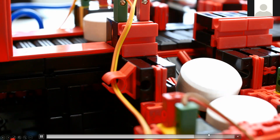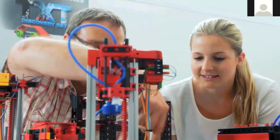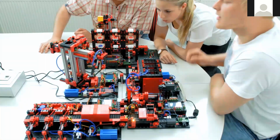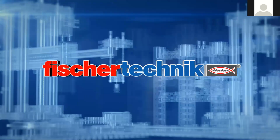Now, as always, the 24-volt version will require the end user to provide all PLCs, all programming, and any other hardware required. Again, each station on the 24-volt version has a relay board for motor polarity reversal and both a multi-pin connector, again 34 pins with a grid of 2.54 millimeters, as well as additional PCB terminals with push-in connections for all inputs and outputs.